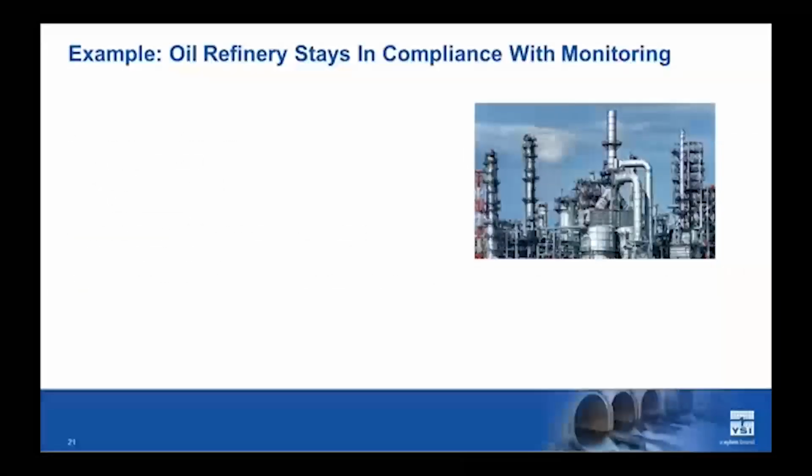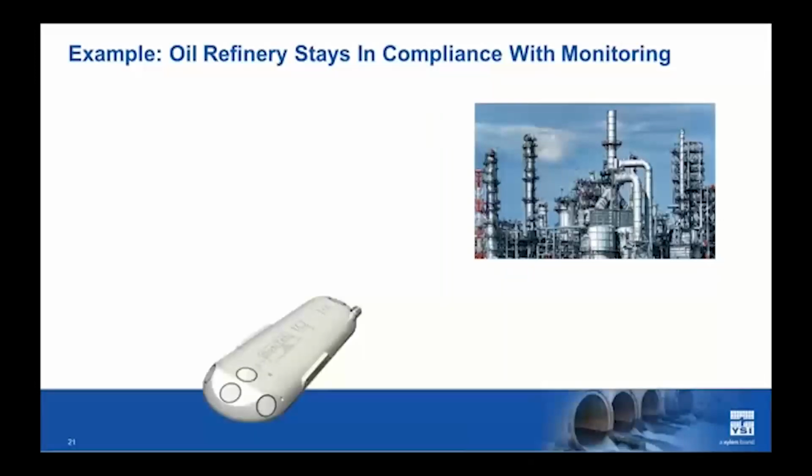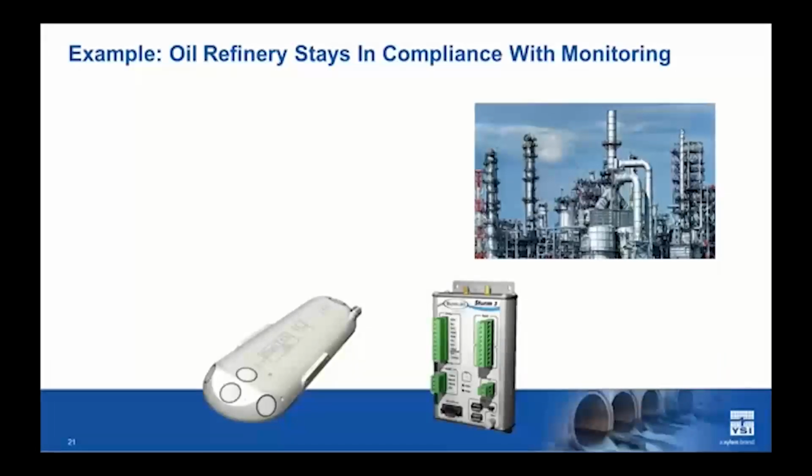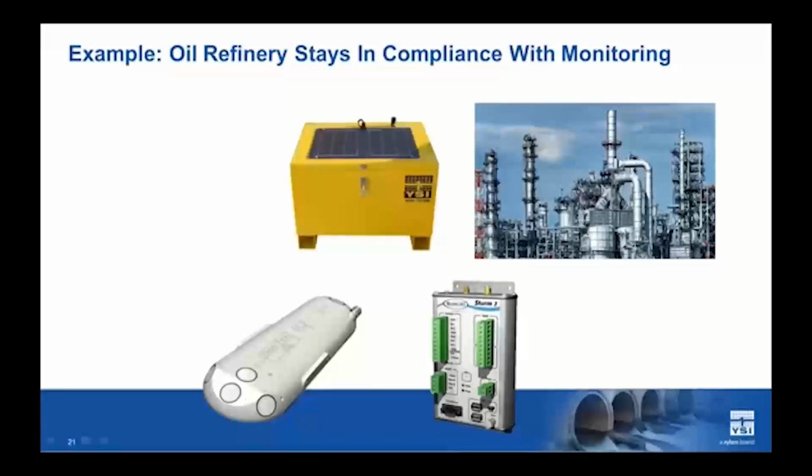So in this situation, for this refinery, they started with what's called an IQ. A Sontec IQ is a Doppler instrument that allows you to measure volumetric flow. And they coupled that with a storm data logger and telemetry, allowing them to constantly get cellular transmissions of the readings from the Sontec IQ. So the Sontec IQ is giving them that volumetric flow measurement. The storm and most of the electronics are housed in a case that contains the power system, which is battery, but it is solar recharged.